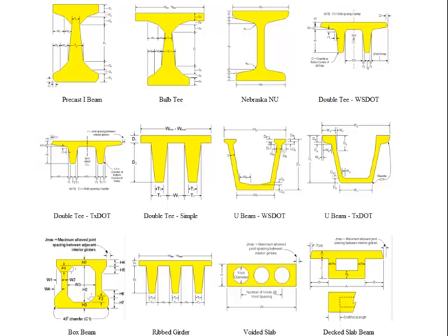Girder sections live in the PGSuper library and describe the geometry, prestressing, shear reinforcement, longitudinal mild steel reinforcement, and the interior diaphragm layout for a girder. Since girder sections live in the library entry, there are two places where you can define and operate on them. You can work either in the master library file using the library editor, or edit a local girder entry directly in a PGSuper project. I find that working directly on a master library file can be laborious.